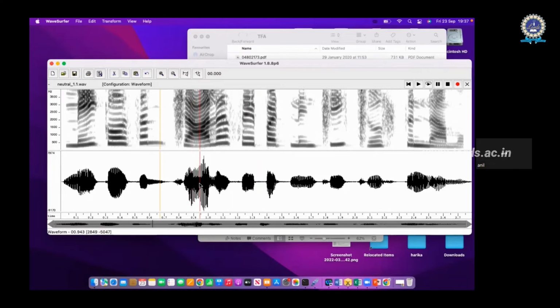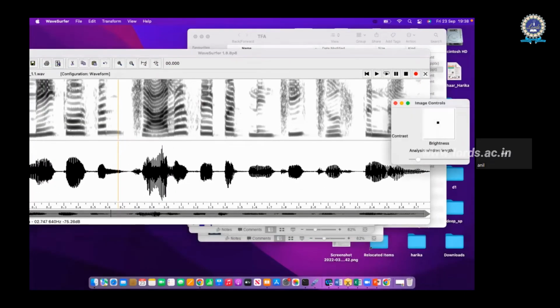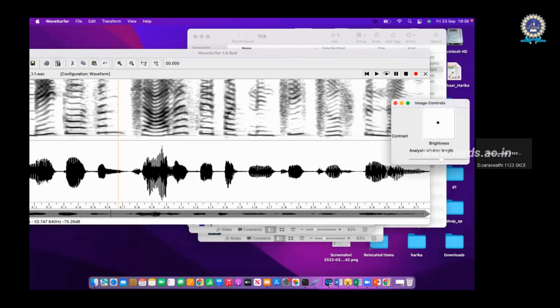Yes. If you take the Fourier transform of any signal, that will be the same. That is called the magnitude spectrum, and it won't change, because there is no variability there. But if you take the short-term Fourier transform, which results in the spectrogram, that spectrogram is not unique. As I just showed you, the spectrogram changes with your window. I am changing the window here, so you are changing the spectrogram. So there is nothing like a perfect spectrum. It depends on my application. I should choose my window according to my signal. That is why there is uncertainty.